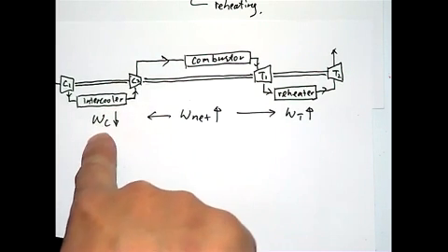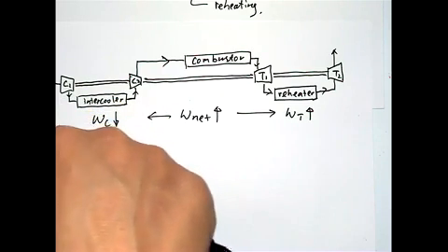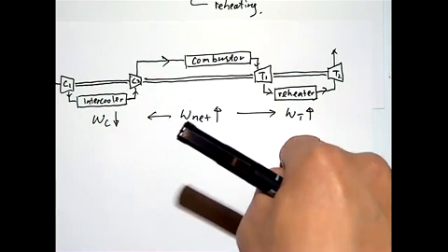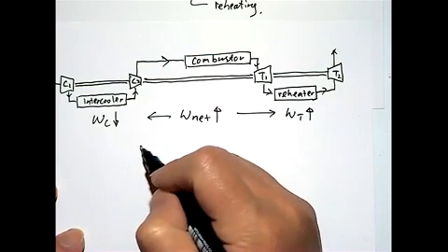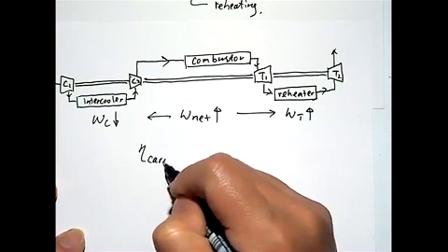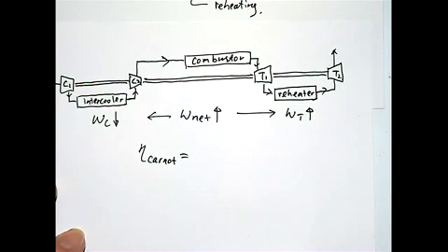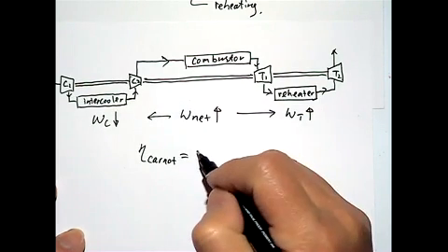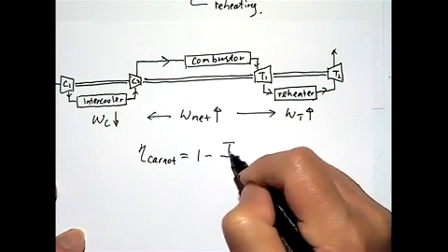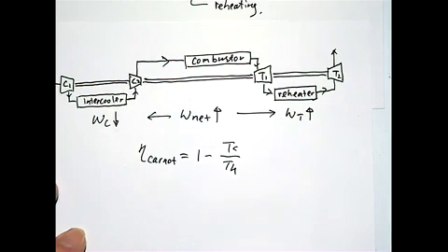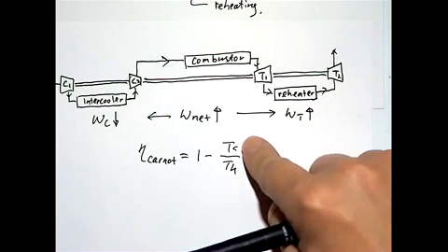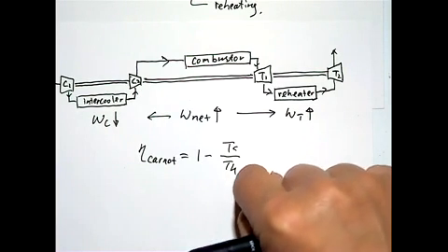So if you're using an intercooler and/or reheater, you gain more work output, but you lose efficiency. The thermal efficiency is lower, and the reason for that is if you're looking at the Carnot cycle or the theoretical cycle in terms of efficiency, we learned that this can be written as T cold over T hot. So this is the temperature of the cold reservoir and the temperature of the hot reservoir, right?